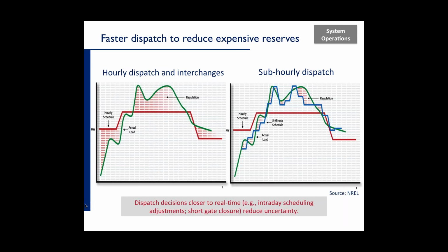It can calculate a fast demand forecast for the next 5 or 10 minutes. And so what you see now is, instead of having a flat dispatch, a new line, which is a blue line, and you can see that it operates in some kind of small stair-step function. And what that means is that the economic dispatch is responding every 5 minutes and can therefore come pretty close to matching the demand.